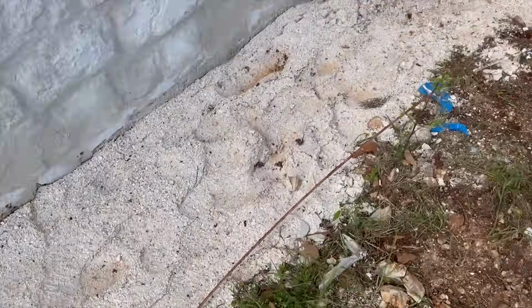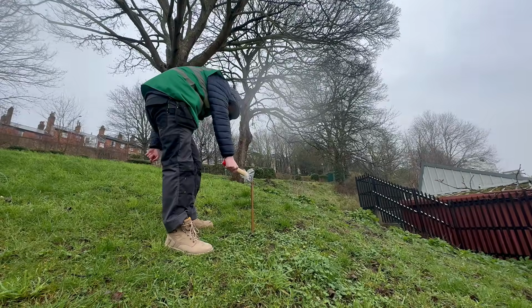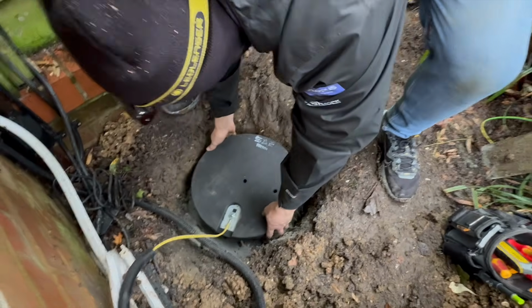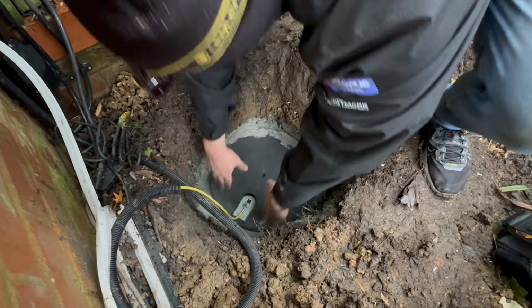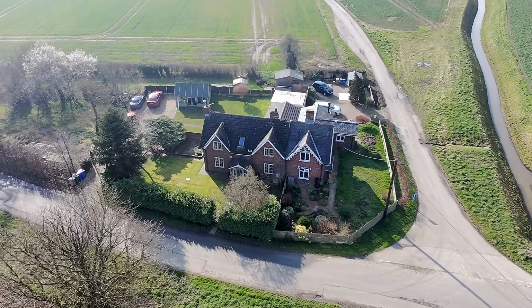Those results can also inform how the earthing system is designed, including how many earth electrodes may be required, how deep they need to be driven, and whether rods, tapes or a full earth grid are needed to achieve the required resistance. Now, although we can change the amount or type of electrodes we're installing, we can't change where in the country they need installing. Can where you live really affect your resistance readings that much?